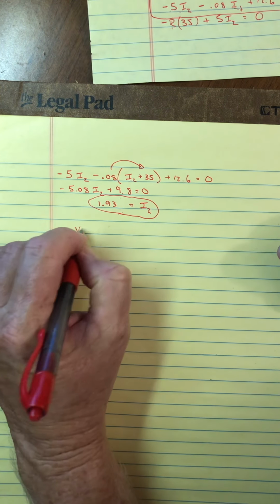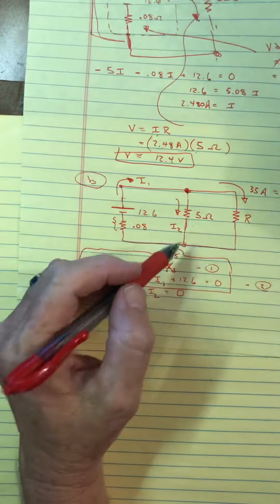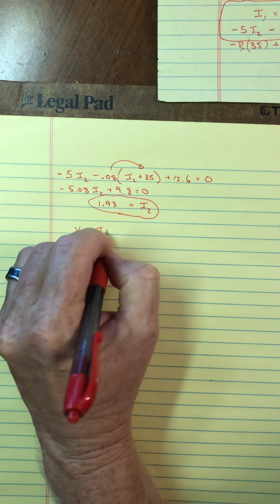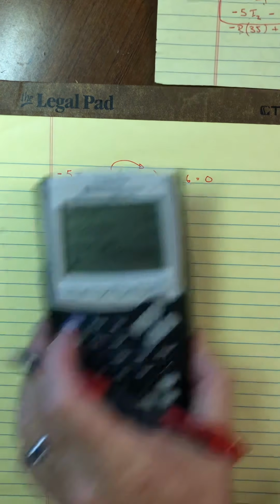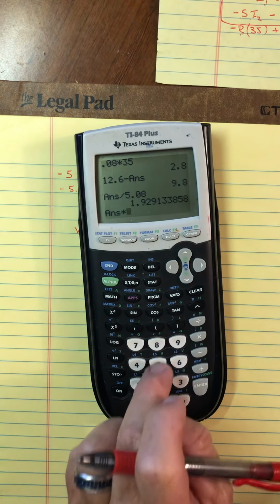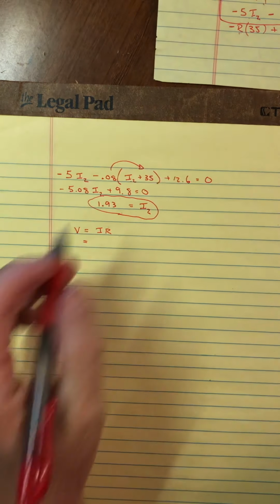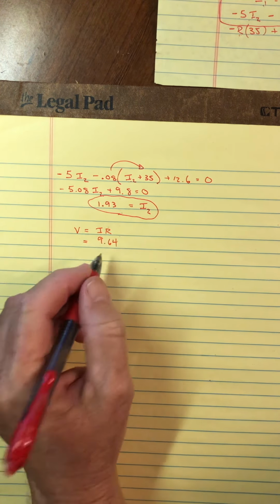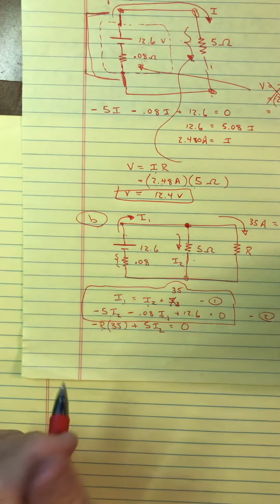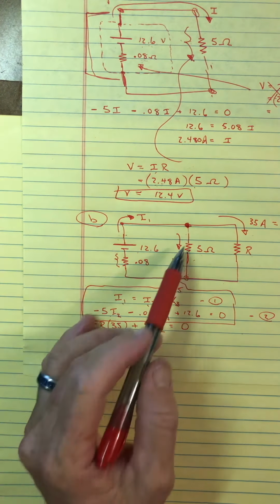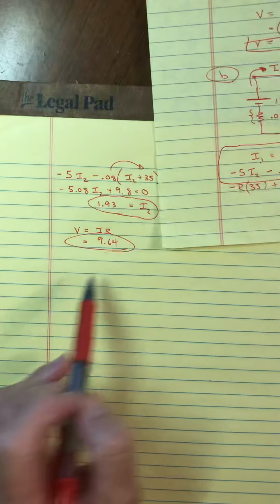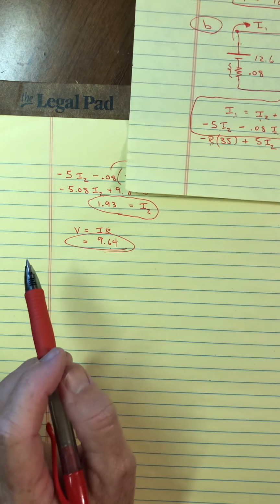So now to get the terminal voltage, I'll just do what I did before. Now that I got the current through the battery, I'll just multiply by the resistance. So let me take that current and multiply by a resistance of 5, and we're looking at 9.64. And hopefully that makes sense. And now the terminal voltage has dropped. And of course now the lights are kind of struggling. That's a low voltage to run your lights, and for that matter your starter motor. So it's starting to drop.